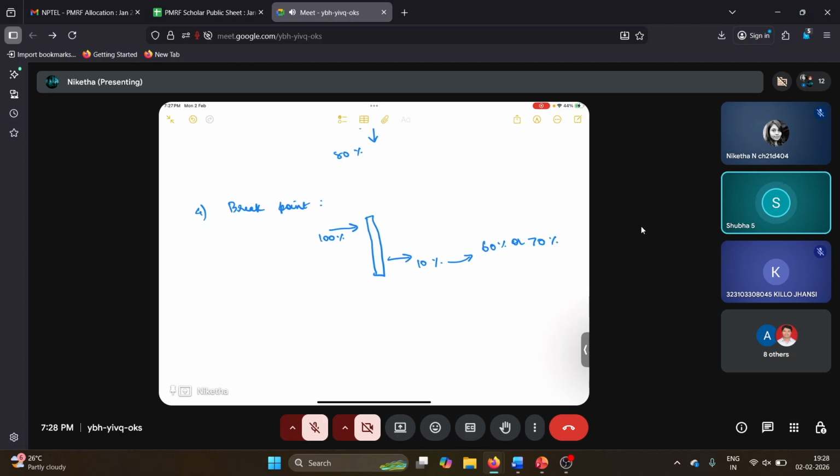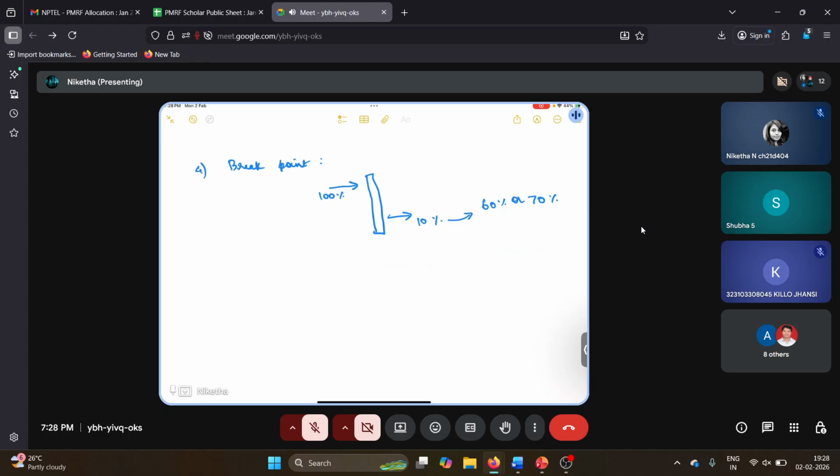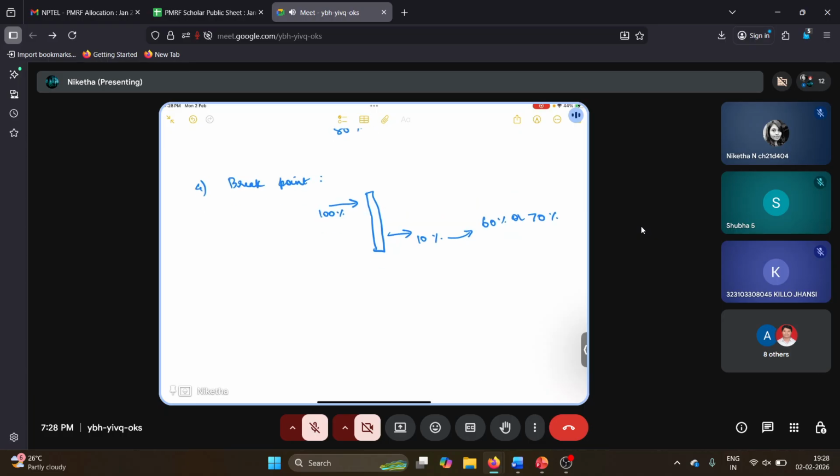After that, the ions will exhaust, and that point is known as exhaustion. Breakpoint can happen at any time. Even if the resin is not completely exhausted, breakpoint can happen. Breakpoint simply means the outlet concentration of ions is high enough that it is not acceptable.